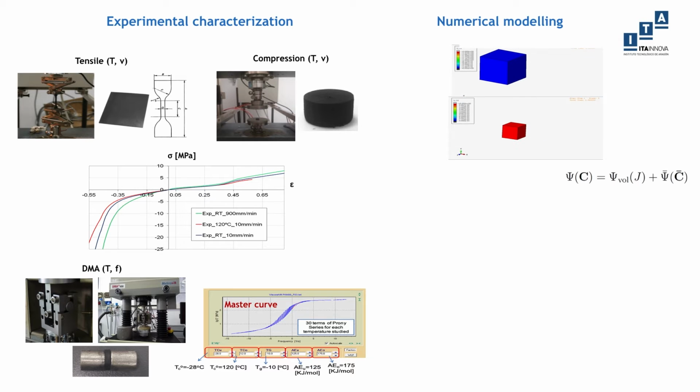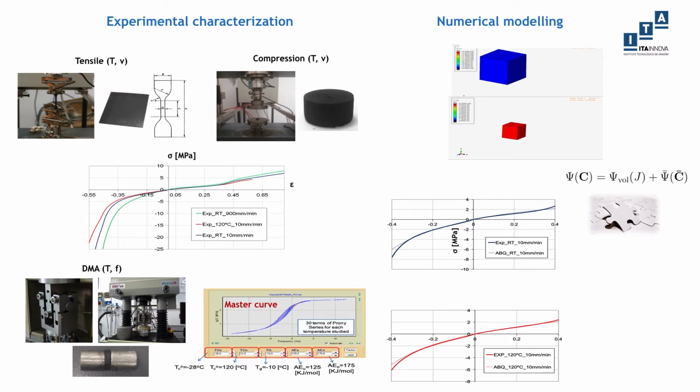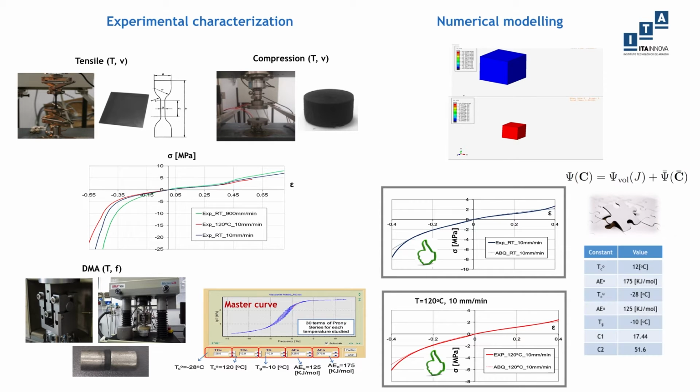On the other hand, the tensile and compression tests are simulated for the different experimental cases using patch test models, which consider real test conditions of temperature and strain rate. The material parameters that feed the constitutive model are fitted so the experimental and numerical stress versus strain curves match in the strain range of interest for this kind of sealing applications.